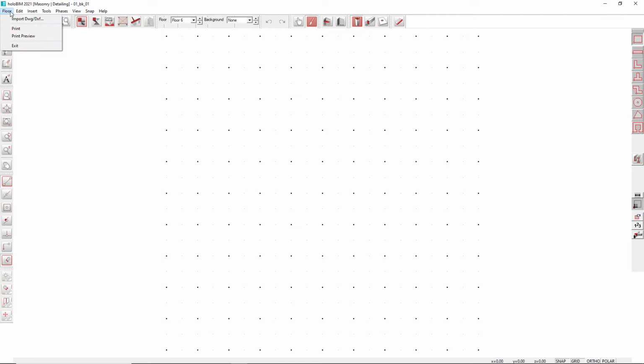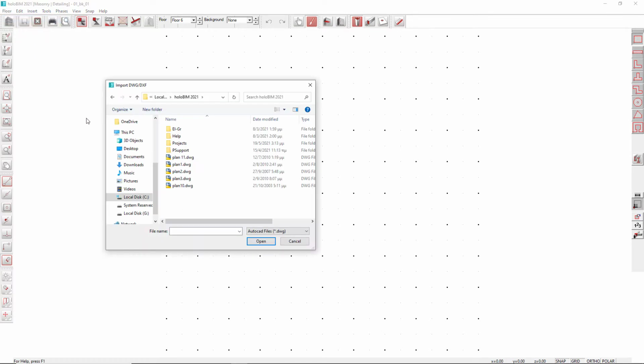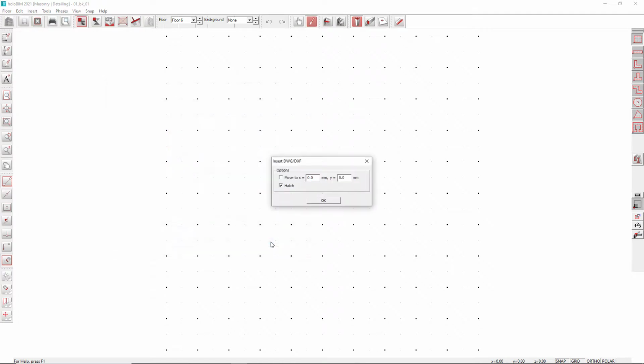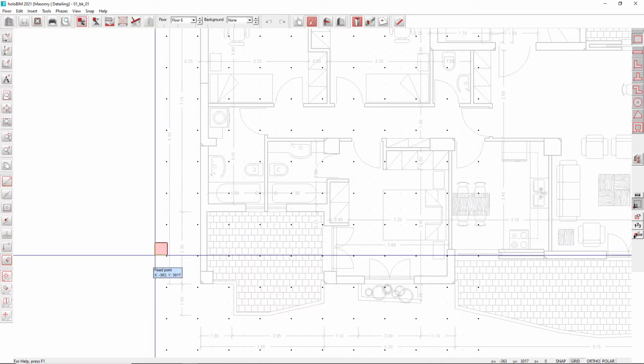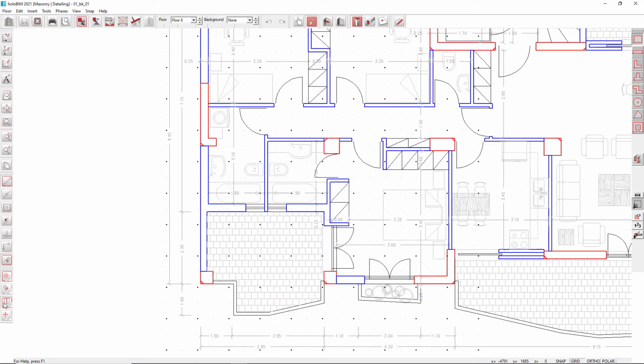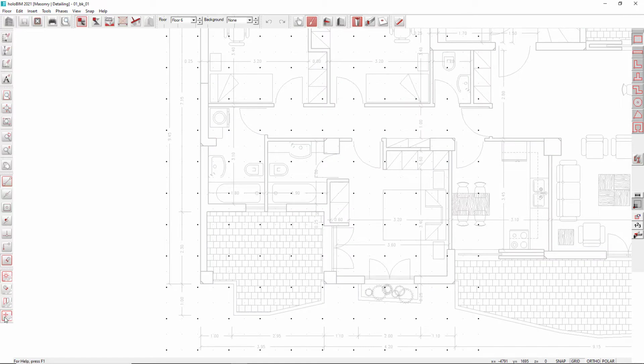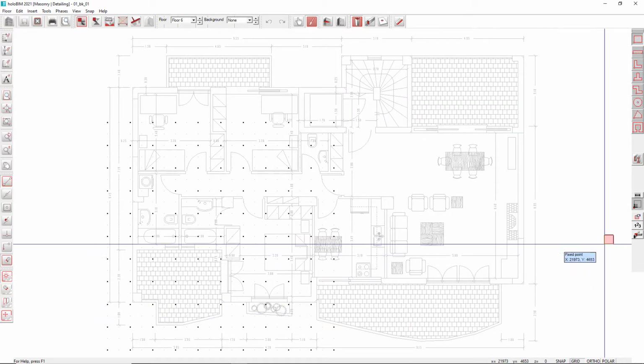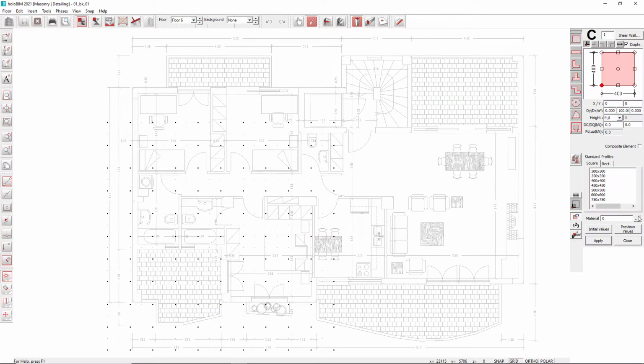We can drastically decrease the time needed for the description of the various structural elements by using an architectural drawing as background of the working layout. The imported drawing is dynamically processed, and the OSNAPS tools can be used in order to specify the insertion points of the structural elements without having to use the exact coordinates for each element.